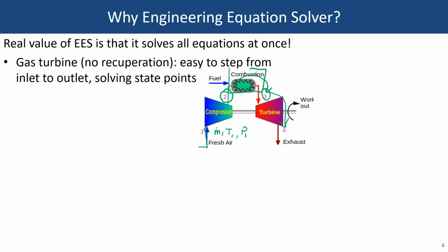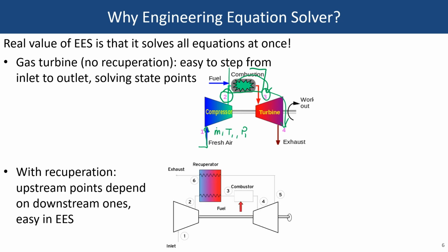So that works in some situations, but just to think about a variation, let's talk about a so-called recuperated Brayton cycle, and this can often be a more efficient cycle. In this cycle you have an additional heat exchanger, and what that heat exchanger does is it takes the exhaust exiting the turbine at point 5 and uses the heat from that relatively high temperature exhaust to preheat the gas coming out of the compressor before you add additional heat in the combustion stage.